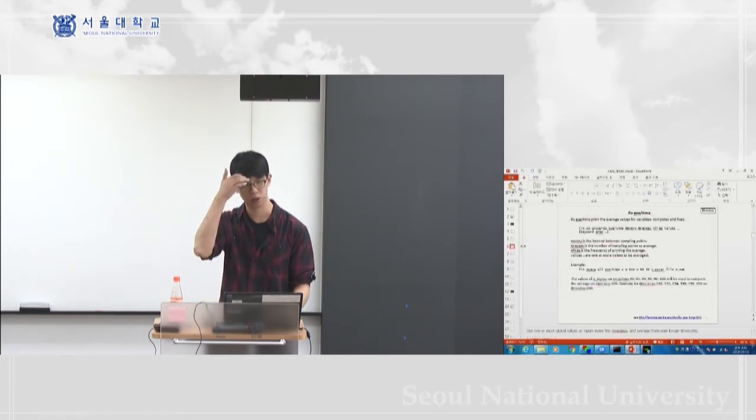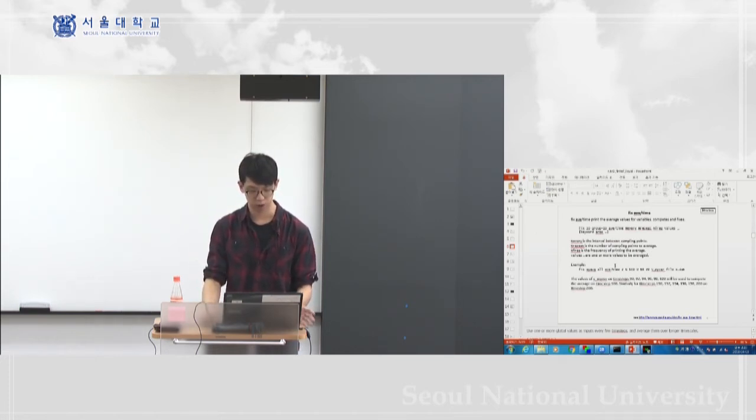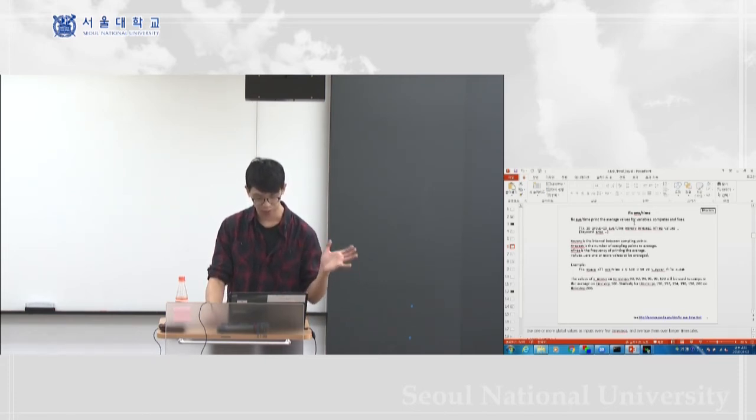But instead of just printing out the MSD, we're gonna average the value for a certain time interval and then print out this averaged value instead of the MSD at a certain point. So in order to do that, we have to use this fix ave/time command. It's gonna print out some values of variables averaged over some time period with some time interval.